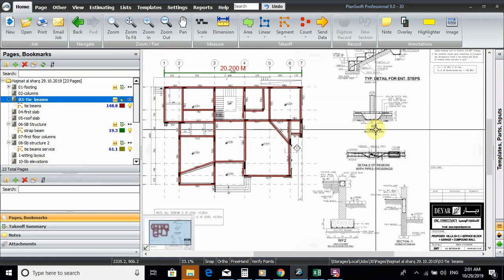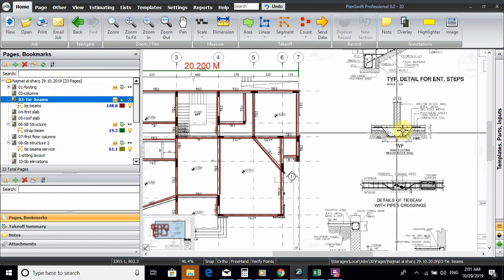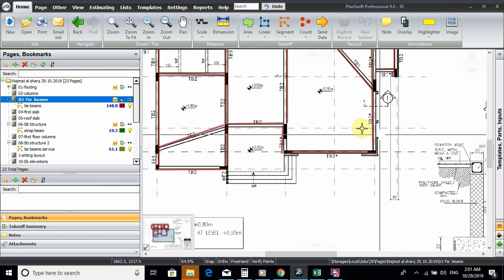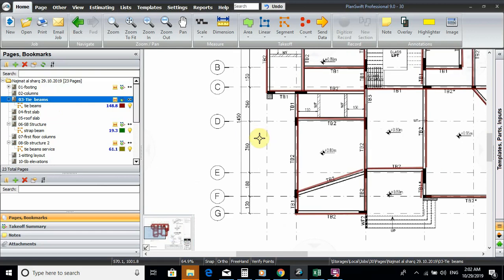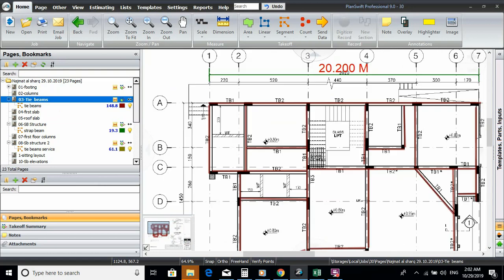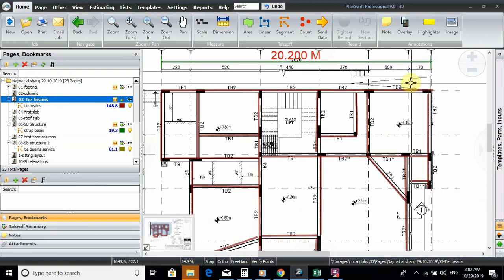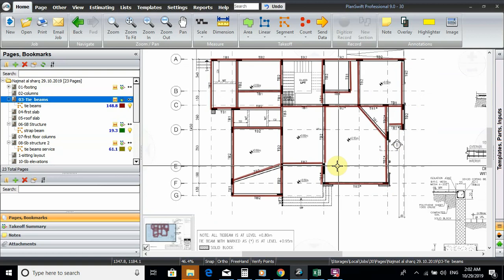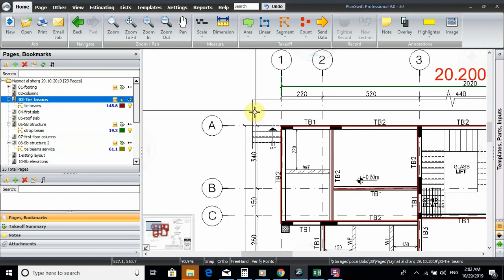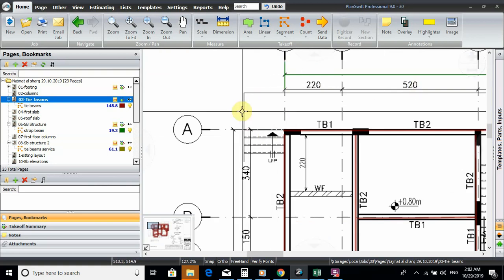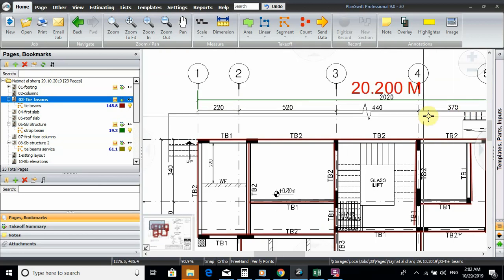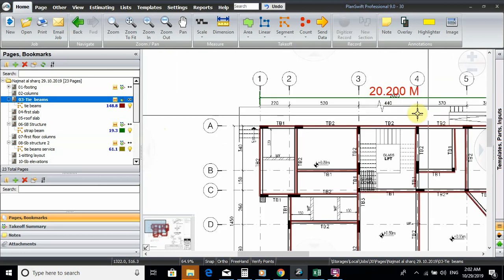Let's go to the tie beam of the villa. There are 2 types of wall footing. Interior wall footing, like this one. And an external wall footing, WF2, which is for the external entrance, and it's not obvious here. Because there is no tie beam here, and as we know, we backfill here, so there has to be some solid block here, because you will backfill this area.